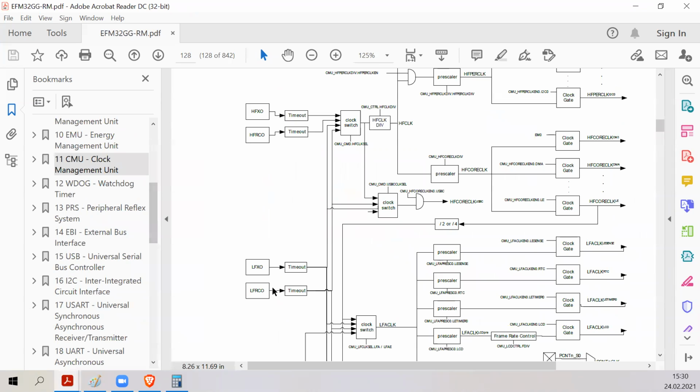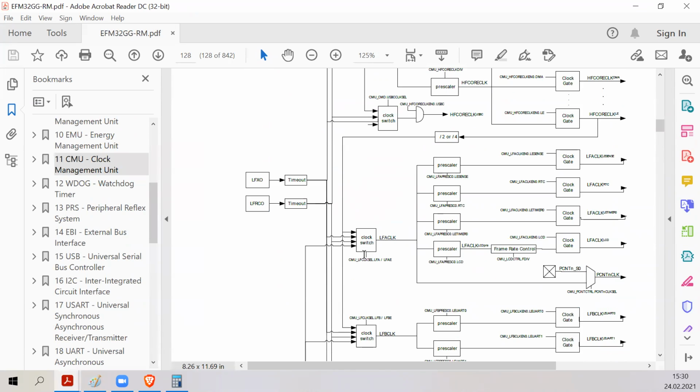So if you are building a device that needs precise timing, which features any kind of clock functionality, and the device will have big temperature swings and maybe supply voltage swings, you need to use an external oscillator. You just have to pay the extra 15 cents and add it to the board.